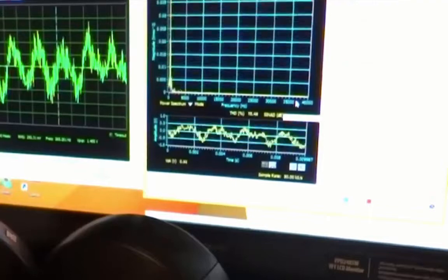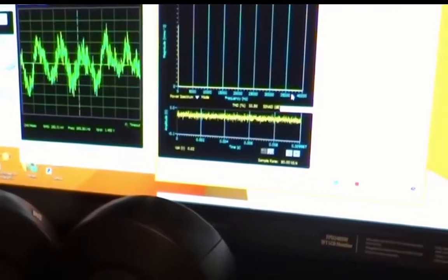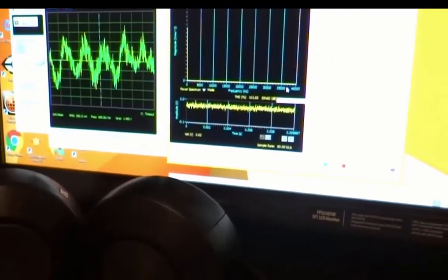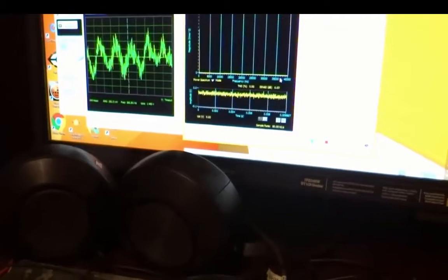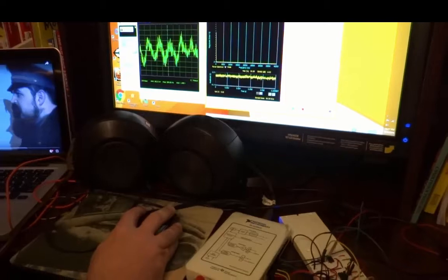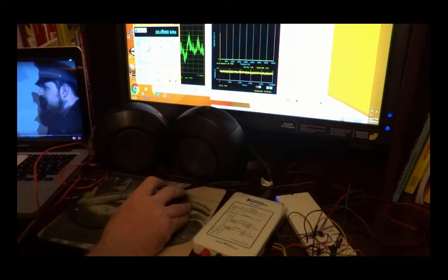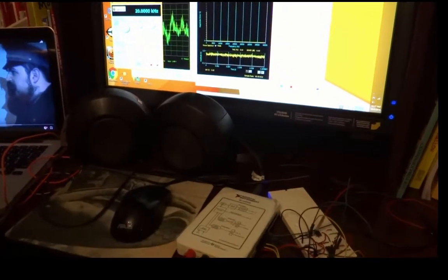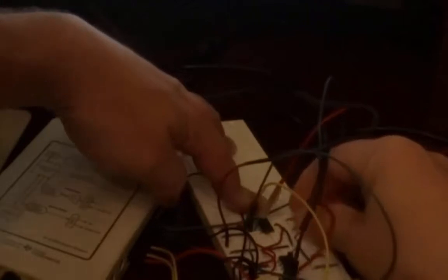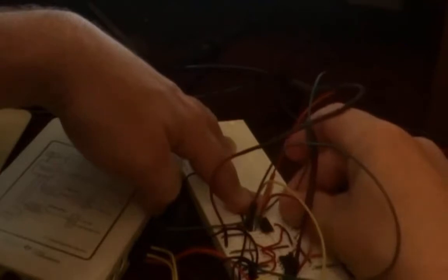And at this point, I will confess to you that I have somewhat enhanced the truth. Although we have been looking at the original Prelude to the Nocturnes signal, what we've been listening to has actually gone through a modulation and a demodulation process, a double sideband amplitude modulation process with the carrier at 20 kilohertz. To see how this works in more detail, I'm going to switch both what we're listening to and what we're watching using the oscilloscope to the output of the modulator.